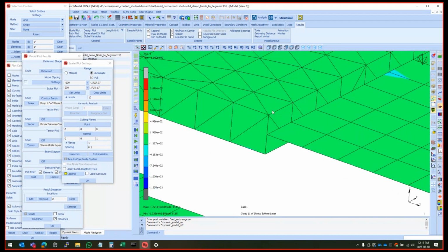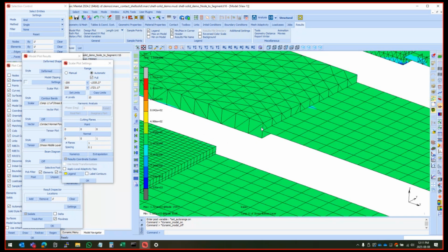If I go to this section, now this is second order TET elements. So there's further complications. There's a mid node there on that shell, which again isn't connected. We're connecting there to, well, in theory, that edge, but there is a node there, but that's a mid node. And that load transfer is going to be pretty strange for a second order element.